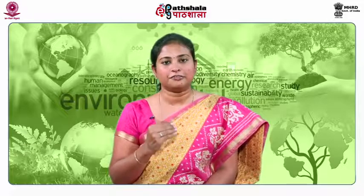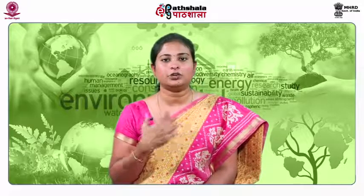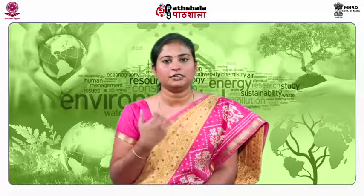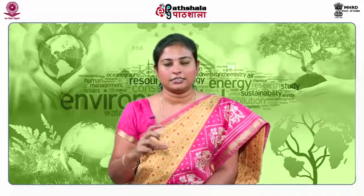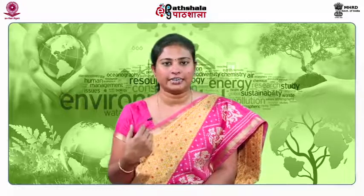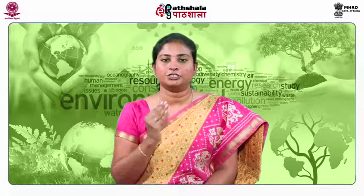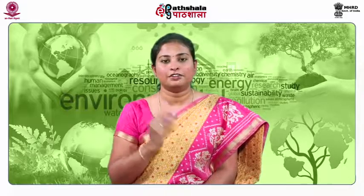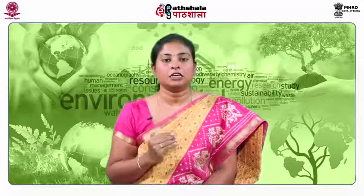The next one is the surface water drainage system. These systems are established generally to avoid water accumulation on the surface of the landfill. It acts like a channel where the surface runoff is collected during precipitation. The landfill bioreactor should be continuously monitored, which gives significance to the environmental monitoring system.